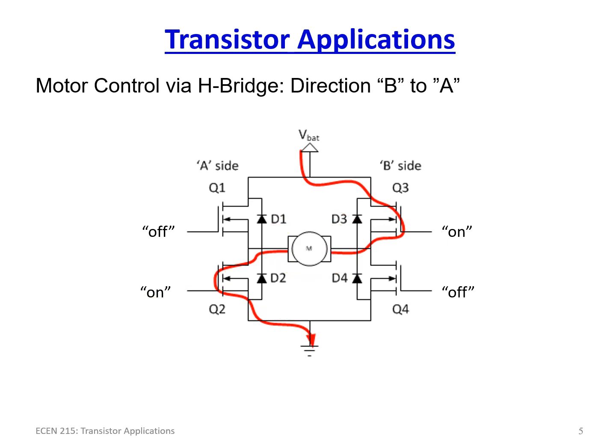Now, one of the more important things to realize is you can never short the H, as they call it. And where an H bridge gets its name is the fact that you now have this kind of symbology. We have the A side and the B side, and then we have the load here in the middle. Hence it's known as an H bridge, because you're creating the letter H where the load is in the middle of the H. Again, you have these four transistors operating in this condition.